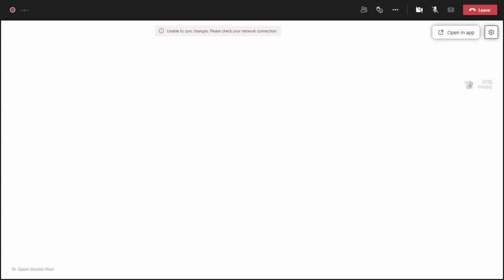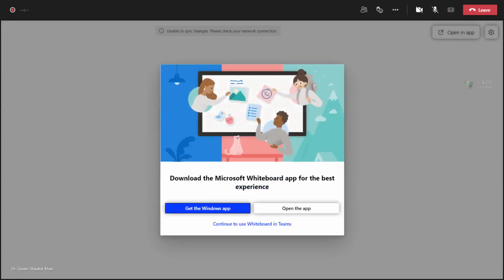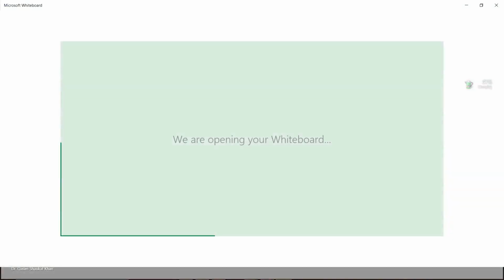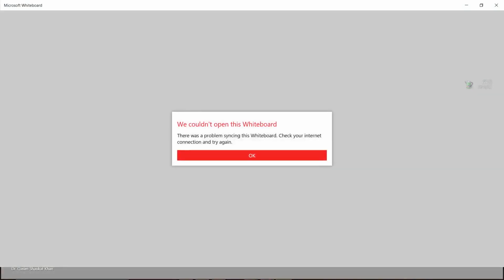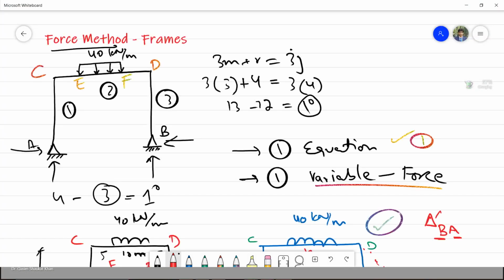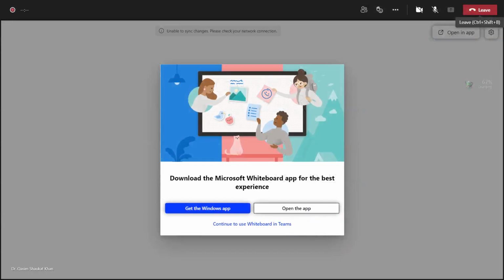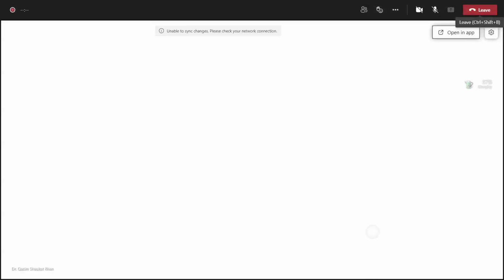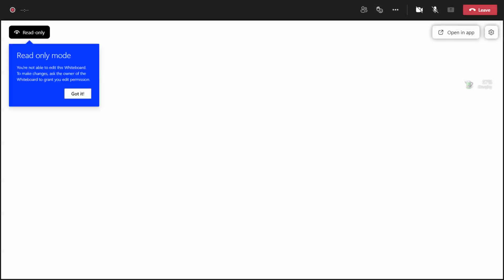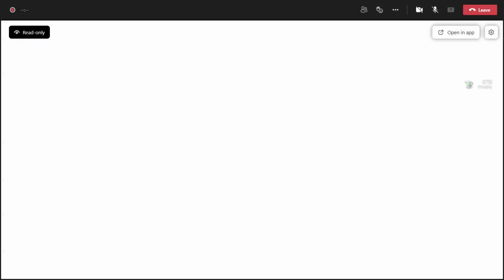Yes, sir. Done. Okay, next please calculate the resultant or radius. It is the square root of (epsilon x minus epsilon y over 2) squared plus (gamma xy over 2) squared. Please calculate the radius or the resultant and let me know the answer. It is 0.000309. It's already a very small value, so round it.